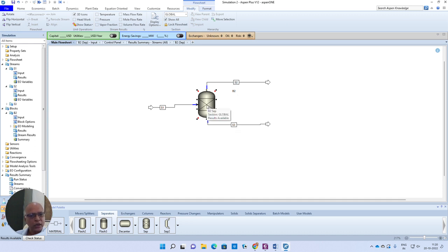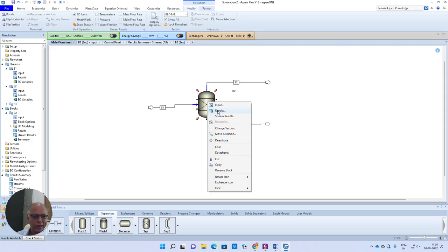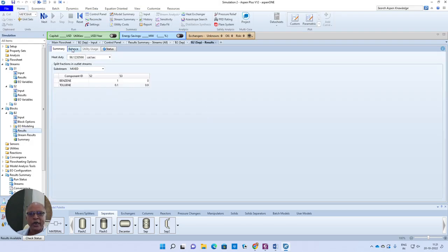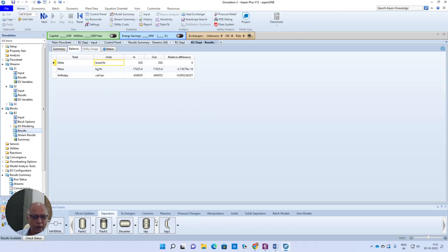Remember, even though this is a simplified model, it will be able to perform the mass balance as per definition, as well as energy balance. Now, the energy balance will not change just because this particular model is replaced by something like a distillation column. Of course, in the case of distillation column, maybe you have other units coming in which will affect the energy balance, but the quantities of energy entering through stream 1 and stream 2, stream 3 will not change, as long as you keep the property method the same, right? This is how the calculations are done in the case of component separator.